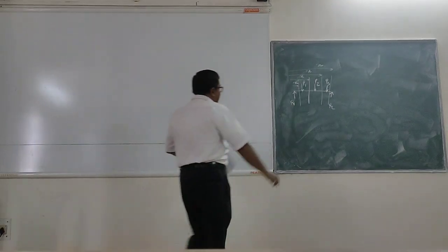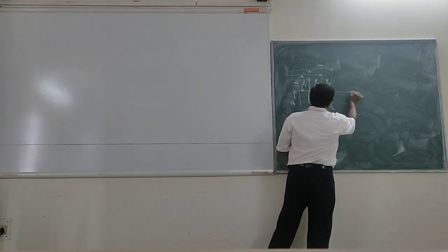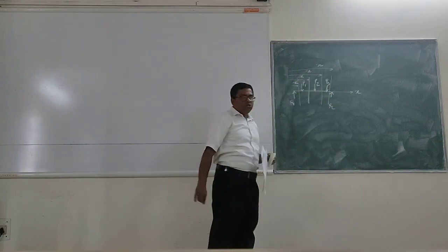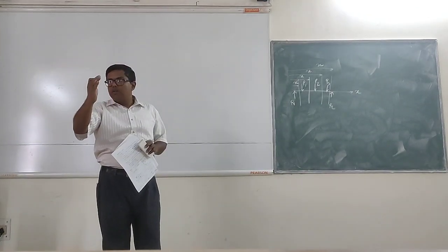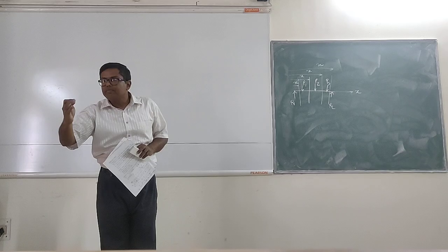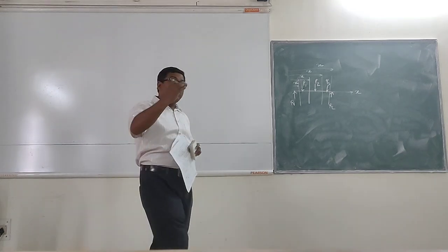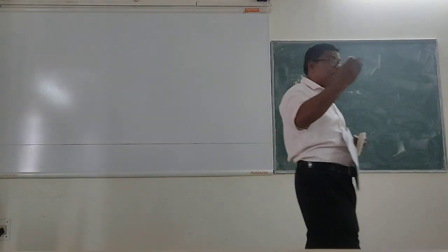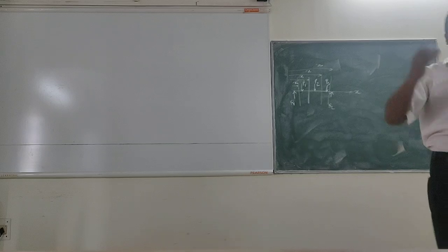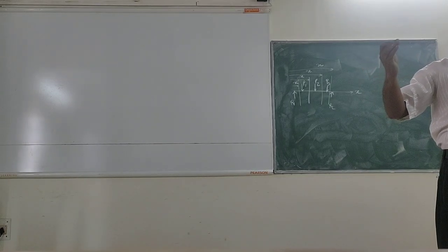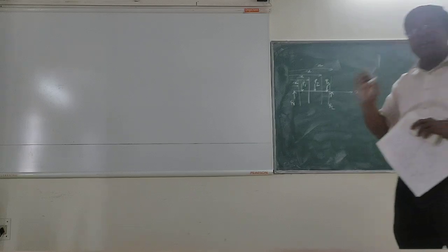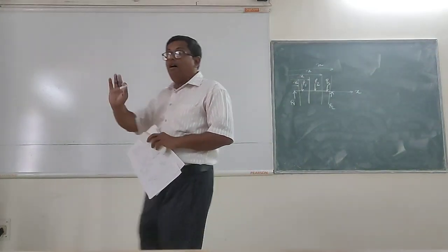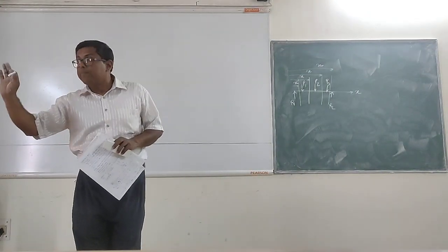If I take X along this direction, every step I am stepping forward and crossing a load, my moment equation will change. However, with a beautiful concept, if X becomes more than some value, that term will become equal to 0. I will try to explain it using this equation concept, then it will become clear.